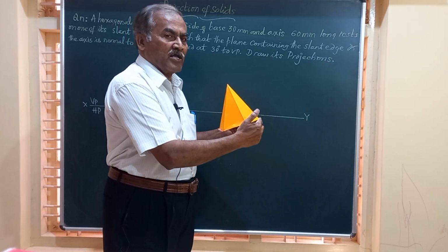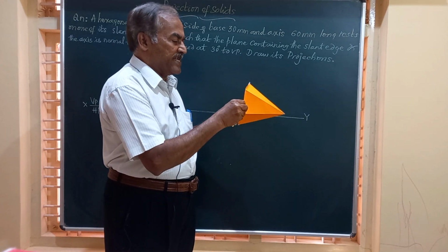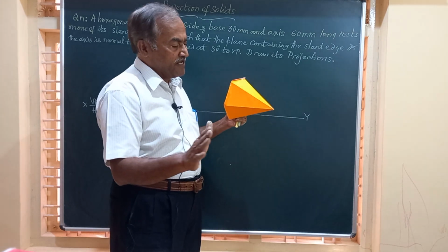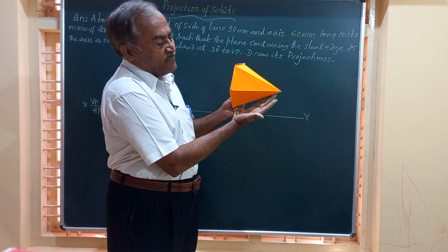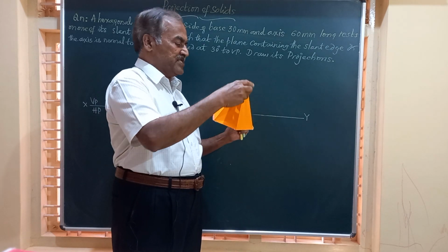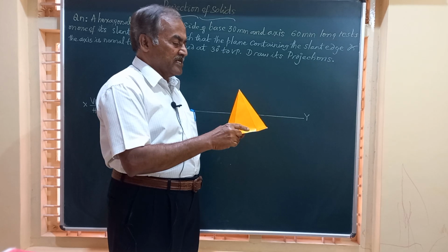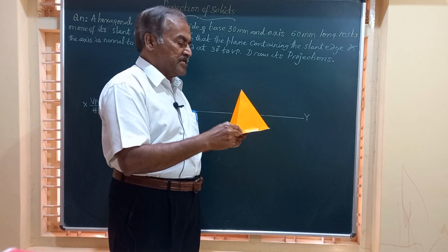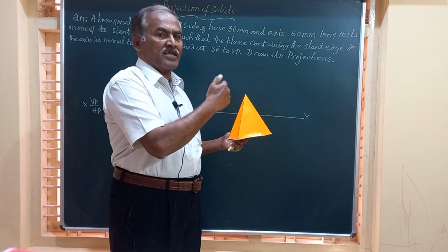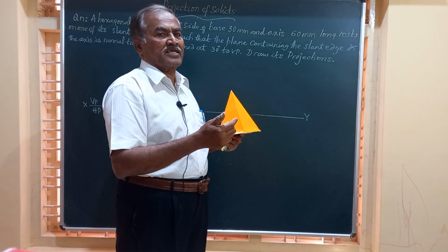Then you get a corner to your right side, and next when you just rotate like this, it will rest on the slant edge on HP with the two triangular faces making equal angle with HP. So basically, I should get the top view, a hexagon in which the two parallel base edges are parallel to VP, such that one of the corners will come to your right side.